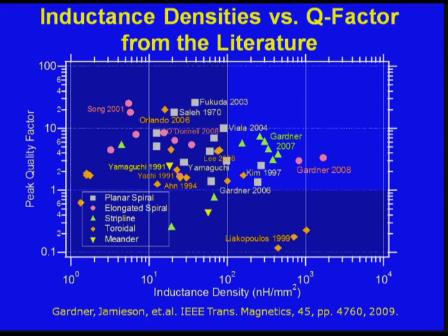And indeed, you'll find that a lot of these particular designs, looks like my pointer died. I'll have to do the battery change. A lot of these designs actually only show about a 20 or 30% increase in inductance when they introduce the magnetic material. So that means that you're not going to be able to convince any fab or product designer to include the production costs of magnetic materials into your process if you're not going to be getting that much benefit from it.